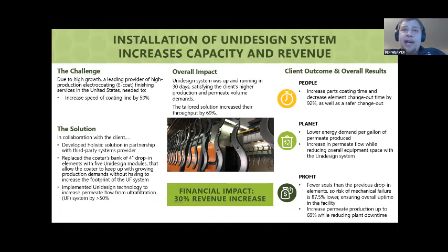And so really there were a number of benefits from implementing this new technology from Solecta. Number one, they were able to produce the rinse water in the same footprint that they had initially. With a 4-inch bank, they were really constrained on space, and if they were just going to add 4-inch elements to the end of that bank, they didn't have the space to do that.